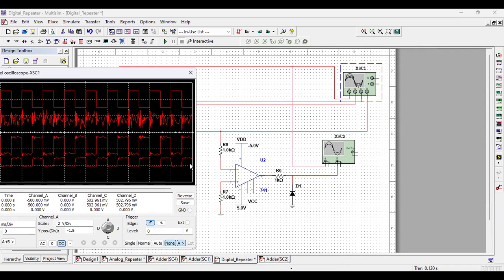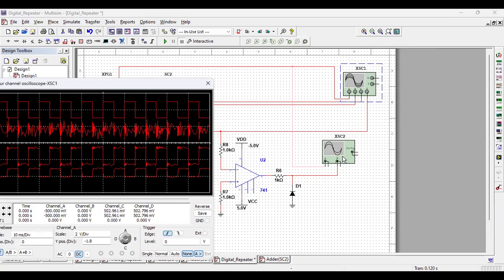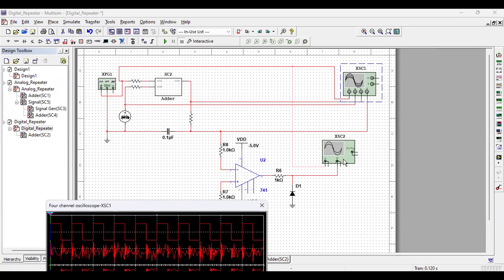These noisy pulses, you can give to a comparator or any kind of flip-flop, a very simple circuit. With the help of these noisy pulses, with the edge of these, you create straight pulses. Here, I have added another oscilloscope, whose number one input is the signal and B input is the pulse shaper output, which is this pulse shaped.